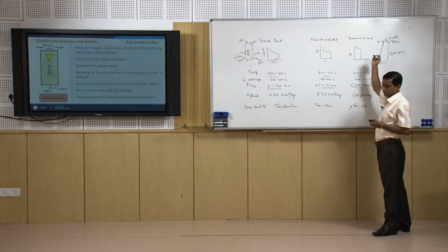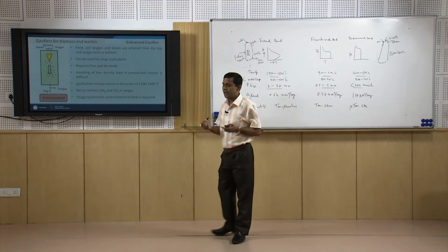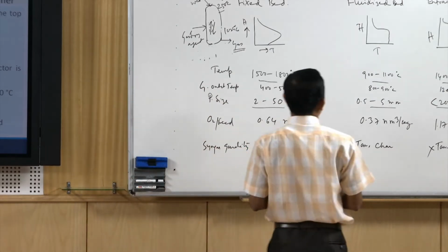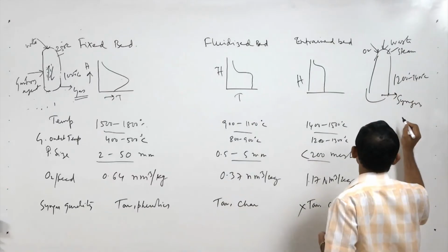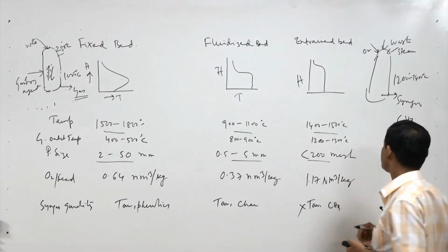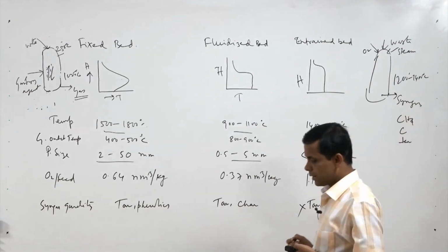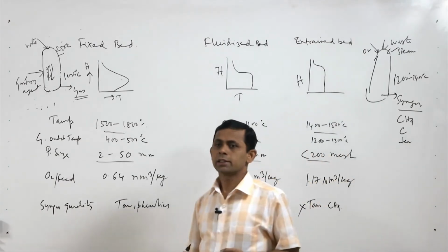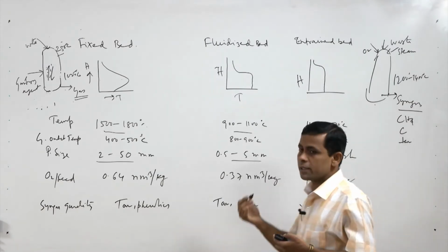That high temperature, high contact time and small particle size all help to get more conversion and to produce good quality syngas. This syngas contains less CH4, no carbon, no char and no tar. This is a superior quality syngas, mostly suitable for chemical production and also suitable for very large scale production.